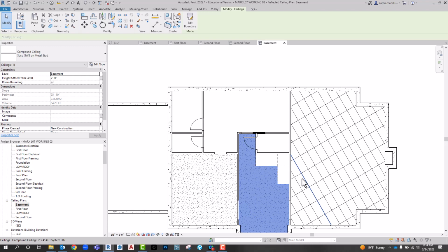So it saves time in theory, but it ends up messing you up when you do sections. So you can do that by creating another floor type. I talked about it in the last video. You can look at it at 9:28, 9:29.